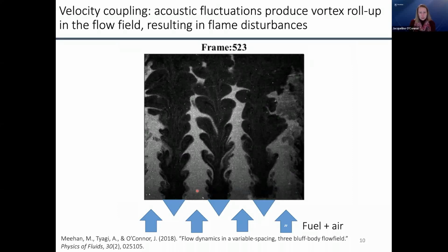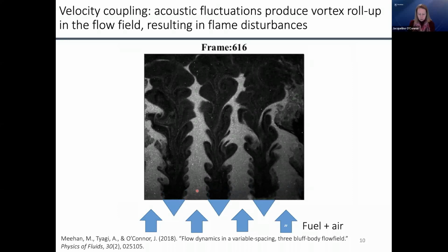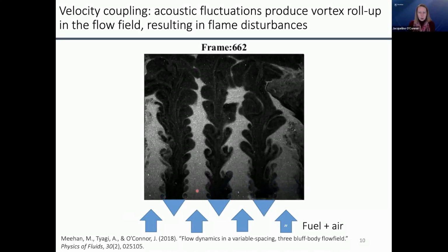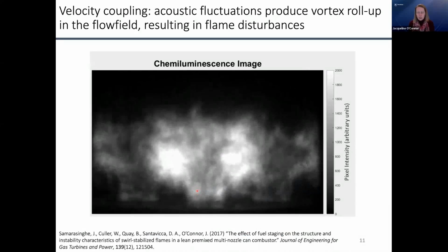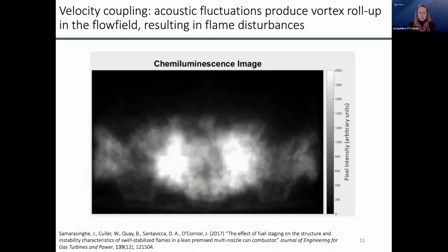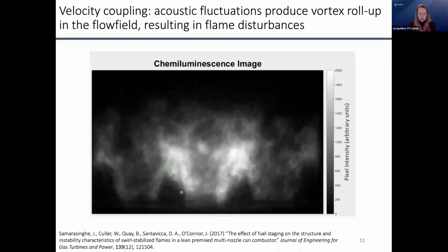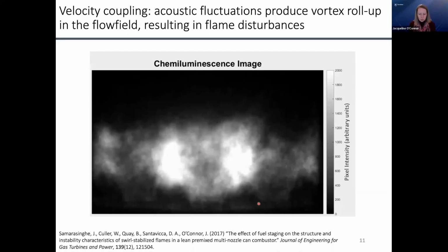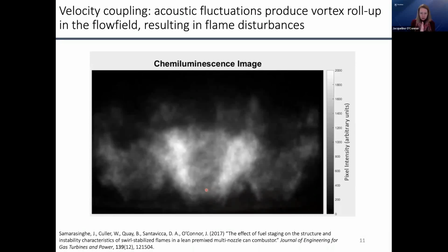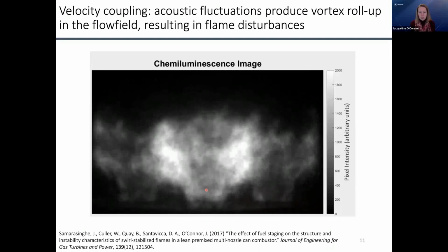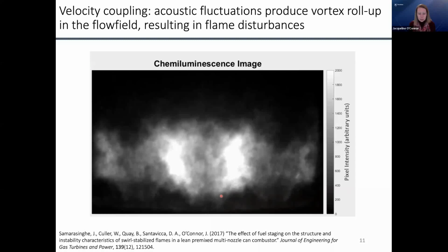This is a really low Reynolds number, right? So Reynolds number 3,000 isn't particularly relevant for most combustion devices. But that combustor that you just saw in the previous video with the sound, this is the high-speed chemiluminescence imaging of that combustor. So you can see there are multiple flames. Here's the one on the left, the one on the right, and then the one in the center looks bright because you're actually looking line of sight through 3 flames. But this is really turbulent. This has a nozzle velocity of 26 meters per second.